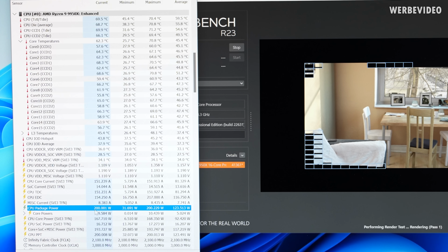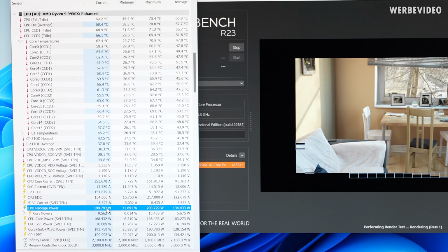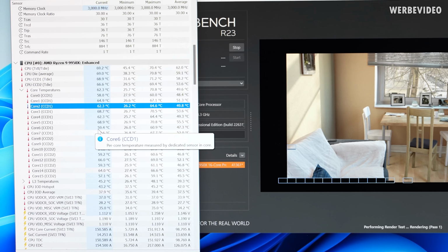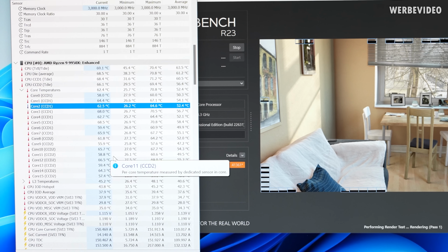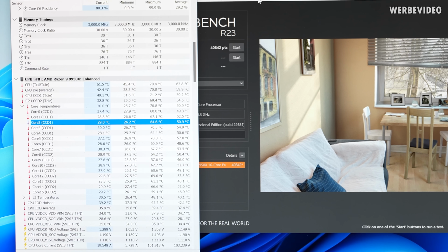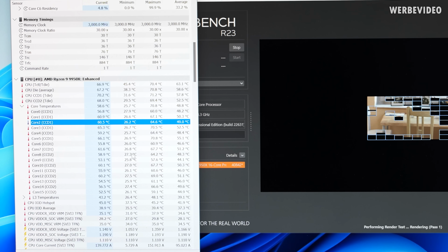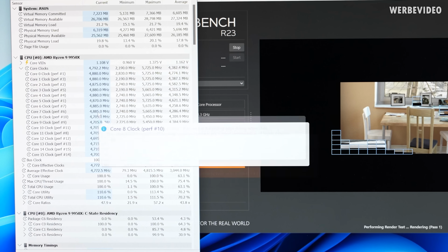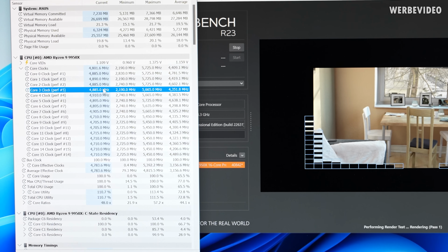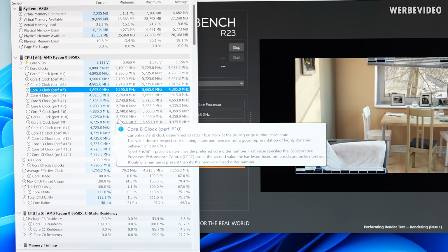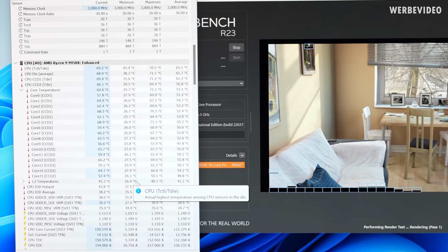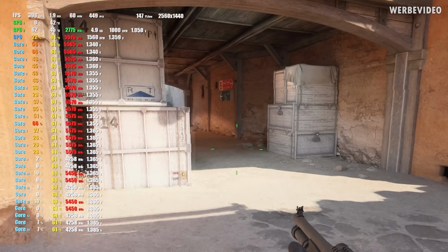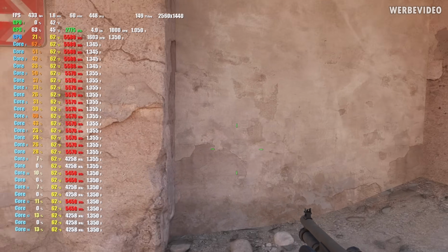So here you can see it's limited by about 200 watt in power consumption, which results in fairly low temperatures. Without delidding, it was maybe 5 degrees Celsius higher. So there was not a huge difference, at least in this state, talking about just running an AIO and basically just replacing the IHS and replacing the indium solder with liquid metal. But you see about 4.8, 4.9, that is the multi-core clock that you have in the stock condition without opening up PBO. In Counter-Strike 2, as you can see, I made sure that always the right cores are getting the load, as I said before.